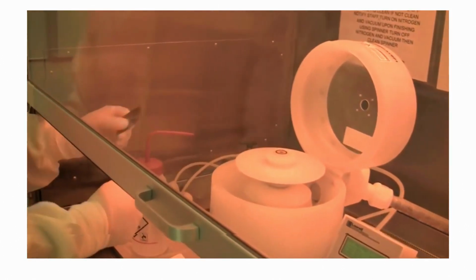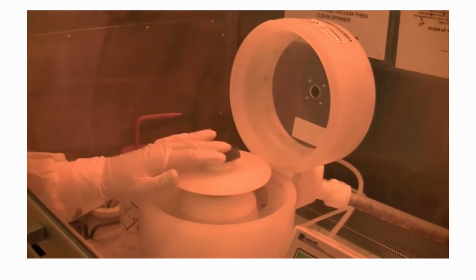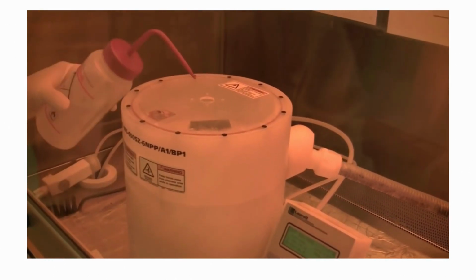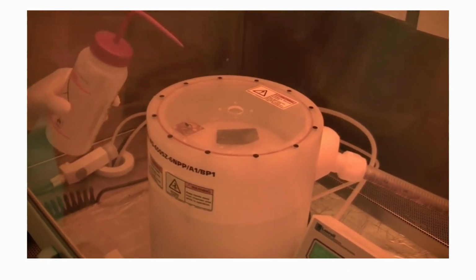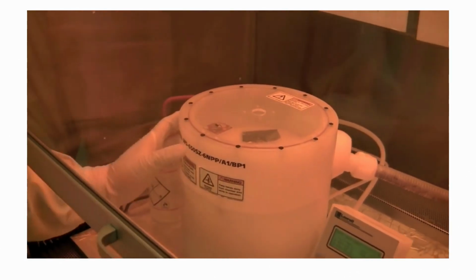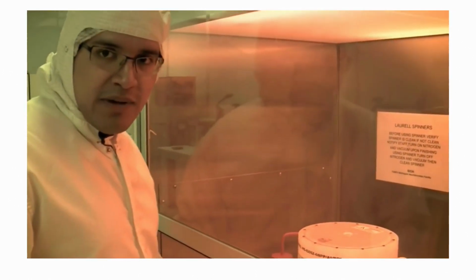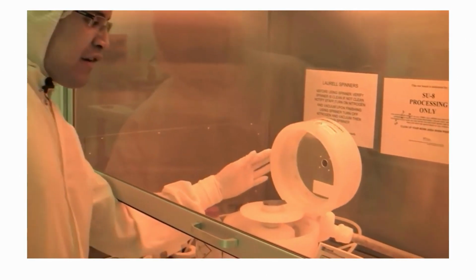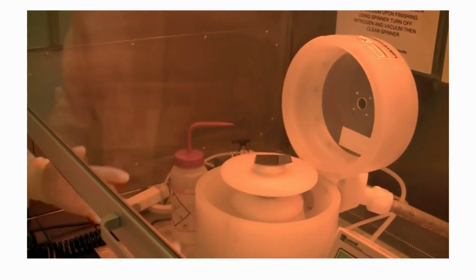I know some users like to do this, and I want to address this. Some people like to put a chuck like this on it, turn on the vacuum, and spin it while spraying in this little hole. Now that's not good for two reasons. First, you're getting acetone everywhere, and some of the pieces, like the motor I mentioned earlier, might get sucked into that area with the electric motor, and it might be a source of ignition, so that's dangerous. Second, you're splattering SU8 and acetone kind of everywhere. It will leak out here and out here, and you're just going to make the whole area dirtier.